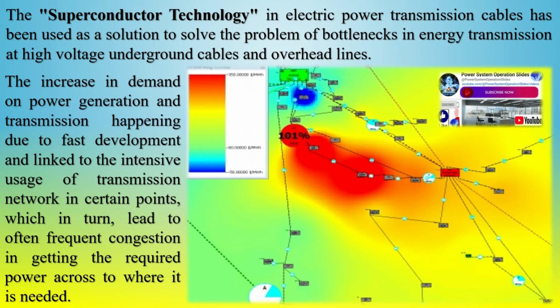Identify and improve resilience. Implement a scheme to identify the transmission bottlenecks and improve the power network's resilience under extreme events. In the quick restoration stage, adjust the operating parameters of undamaged components and maximize the largest power supply (LPS) with limited resources. In the slow restoration stage, identify these transmission bottlenecks and further improve the LPS by expanding the capacities of these links.